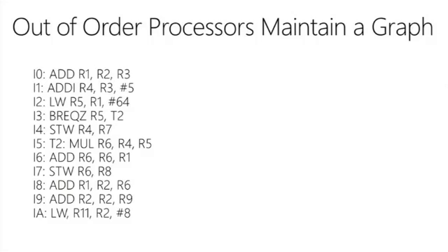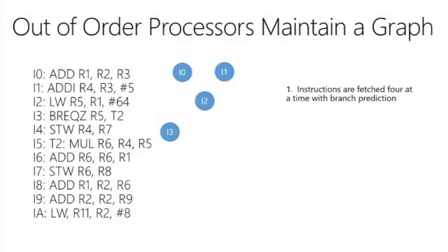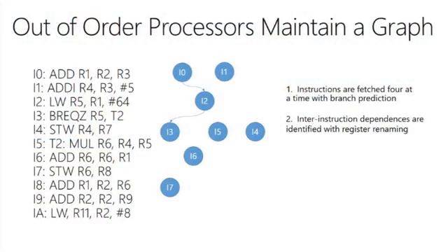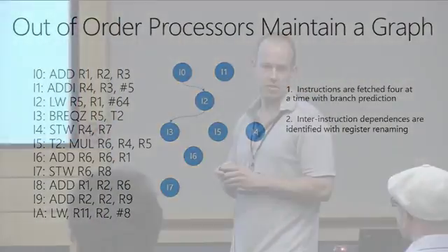So just to get us all on the same page with the various overheads, this is what an out-of-order core does, and I think most of you know this, so I'll be quick. This is your list of dynamic instructions, your dynamic instruction order that gets executed in, say, a RISC ISA. And you'll be fetching some number of them at a time, let's say 4. So you fetch 4, you fetch another 4, you fetch another 4. And then you start doing register renaming to identify the dependencies among instructions. And register renaming requires a fair amount of analysis, and you have to save the rename maps to roll back in case of a branch misprediction.